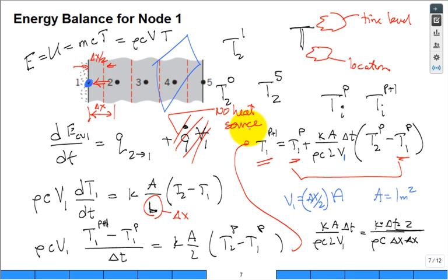Yeah, in this problem we don't have a volumetric heat source. But I show it in case you do have a problem where you have a volumetric heat source, where it would come into the energy balance equation. Like, what kind of keywords should we look for in a problem? Electrical resistive heating, then that's a 2, then rho C delta X. This L right here is a delta X. This V is a delta X over 2 times the area. Those areas cancel.